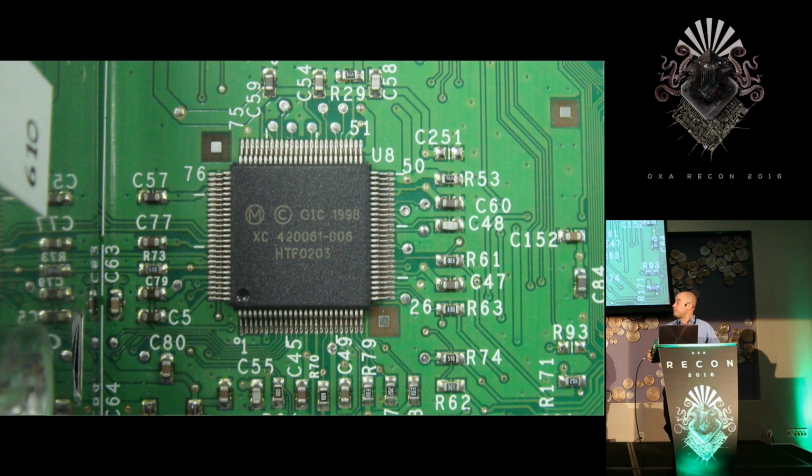This is the ACP chip. It's a 100-pin TQFP package. From the markings, we can see it's a custom system on chip made for General Instrument Corporation, GIC. All of the decryption is performed by the ACP, and all decryption keys are kept only inside this chip. The newer set-top boxes have newer versions of this ACP. My study focused on the original chip that we see here. As long as these set-top boxes are actively used, it's still a relevant target. Whether the newer chips include more advanced security features, or if they exist only for cost saving due to die shrinkage, I don't really know.